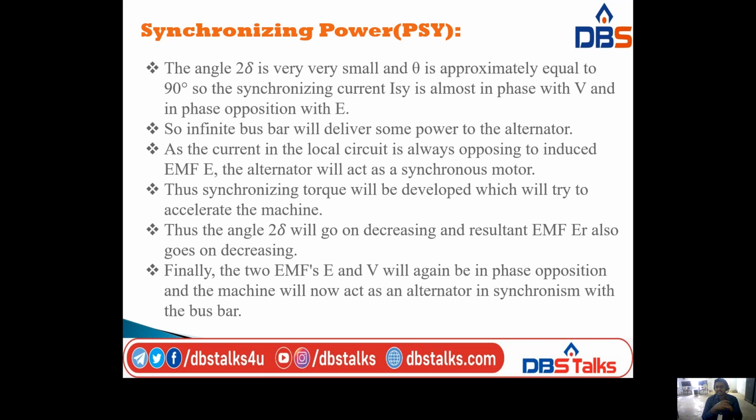So the infinite bus bar will deliver some power to the alternator. As the current in the local circuit is always opposing the induced EMF E, the alternator will act as a synchronous motor.